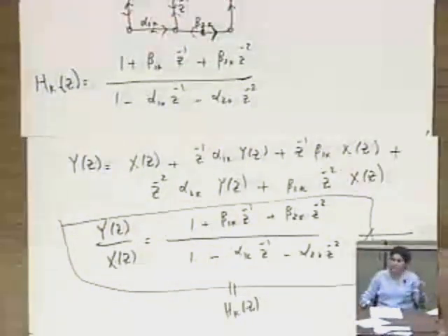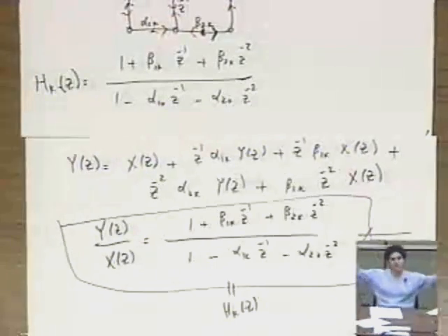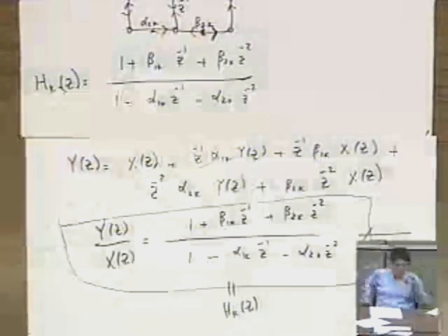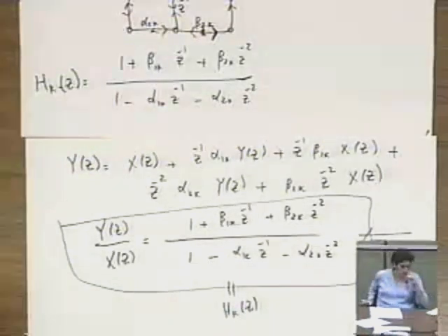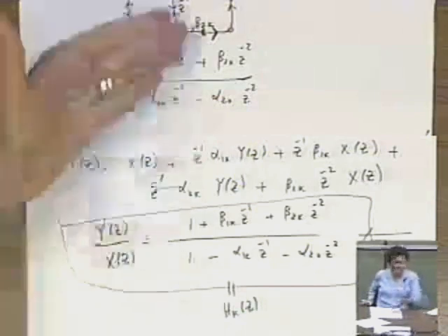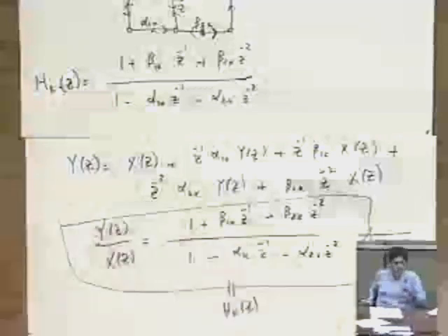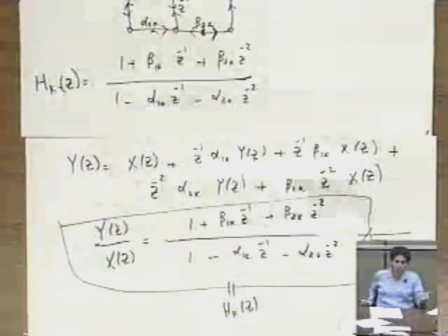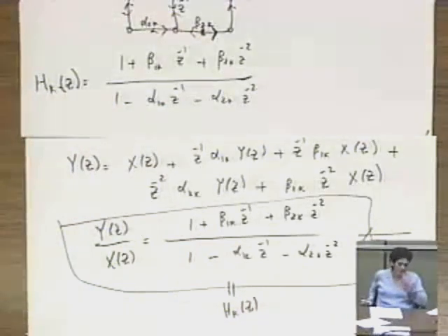We'll do that also when we're dealing with FFTs. We'll also do the same thing where we change the input and output and the direction of the arrows. It's a cute little theorem, and it tells you that more than one second-order system can satisfy this input-output relationship. So this direct form 2, if you will, is not the only way of implementing the second-order system. Okay.